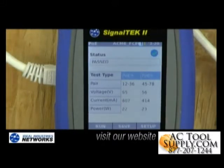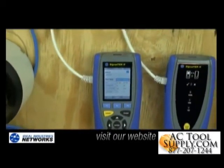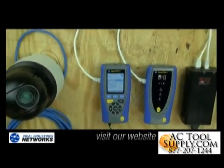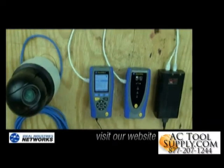Now I'll run the load test, and you can see that the PoE injector I'm connected to shows me what pairs PoE is available on, the voltage level, the current in milliamps, and how many watts are available. Now I can test at the end of a long cable to make sure enough power is getting to the end of the cable to support my IP cameras.